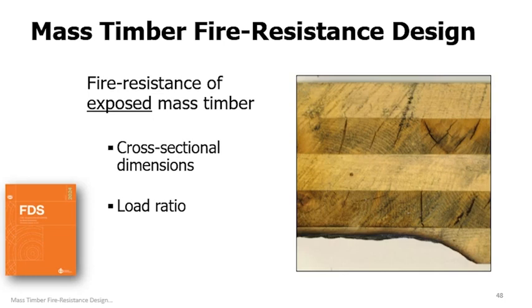If the load ratio on the wood member is decreased to a ratio of less than 100% of allowable stress design, the result will be an increase in fire resistance. This is due to the fact that a smaller ratio would not require as large of a remaining section to continue supporting the load, thereby accommodating greater section loss and hence a longer exposure time.